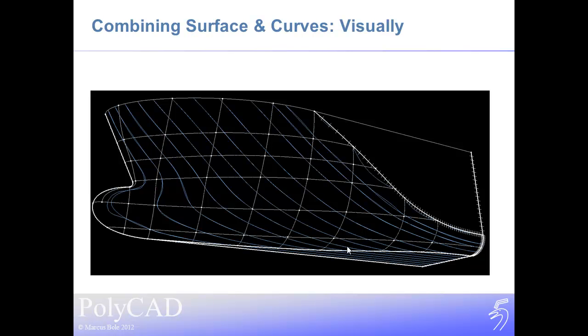So here we have a hull form just showing the buttocks. These buttocks at one level are coming from our surfaces that have been generated across this curve network, and there's another set of buttocks that are being lofted by curves using exactly the same method as previously described. So we start to see some discrepancies. We start to see some discrepancies in areas of the surface that aren't working too well. For example, we start to see some discrepancies down the flat of side here.